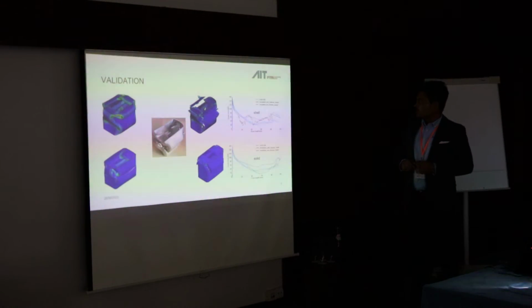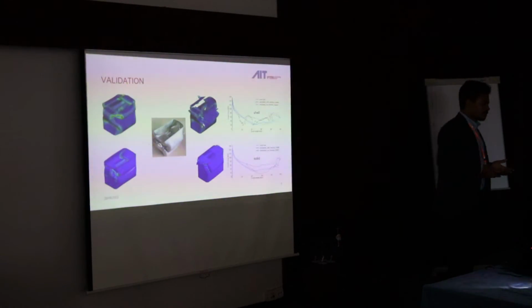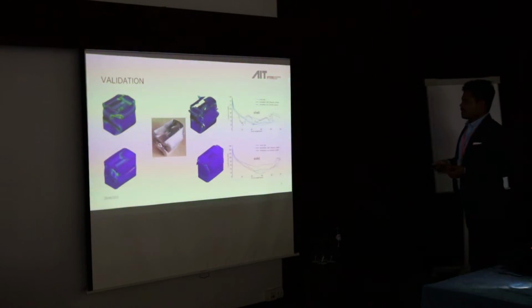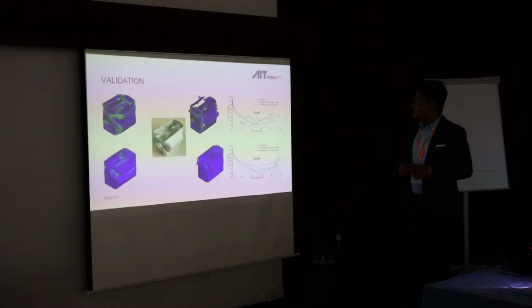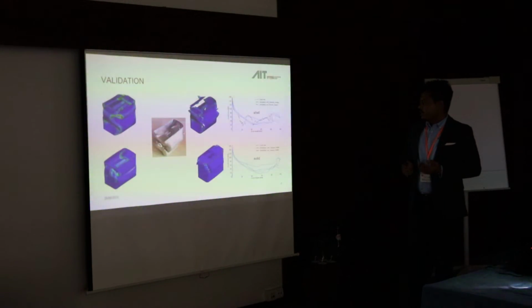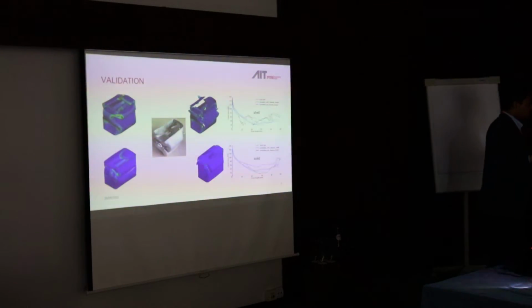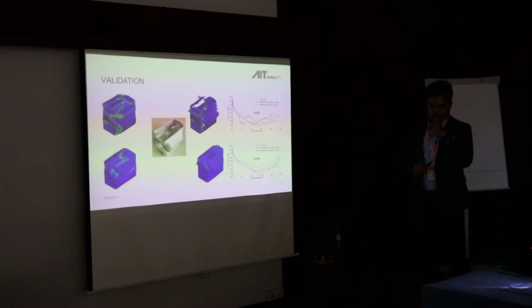If you compare the force displacement curve with the experiment, you can see for both cases, shell and solid, the simulation without any failure model inside over-predicts the force level, which is quite obvious. But the one with the failure model inside, for shell, didn't really work out. It's a bit unstable. But with the solid, we were in fairly good agreement, considering all the simplifications: we ignored the anisotropic yielding, we did not use the DIC measurement to calibrate the hardening curve, and we even ignored the anisotropic fracture behavior.